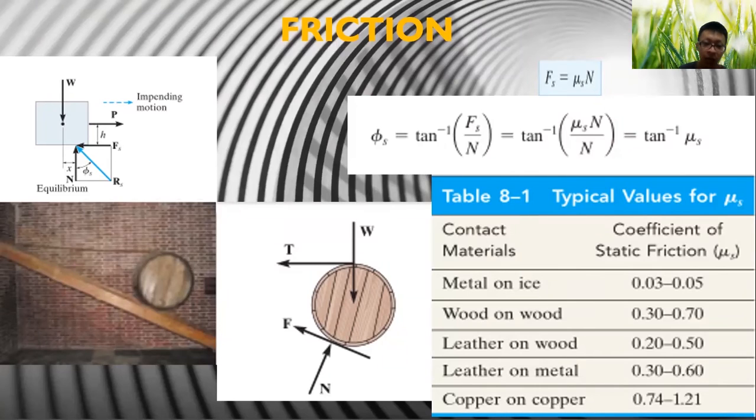So N is the normal force, which is perpendicular to F, the frictional force. As you can see in the left diagram, there is impending motion. Impending motion is a tendency for the barrel to roll downwards from a slope. However, there's friction there, and since there's also a rope, the barrel is in static motion. So the friction will be static friction and not kinetic friction.